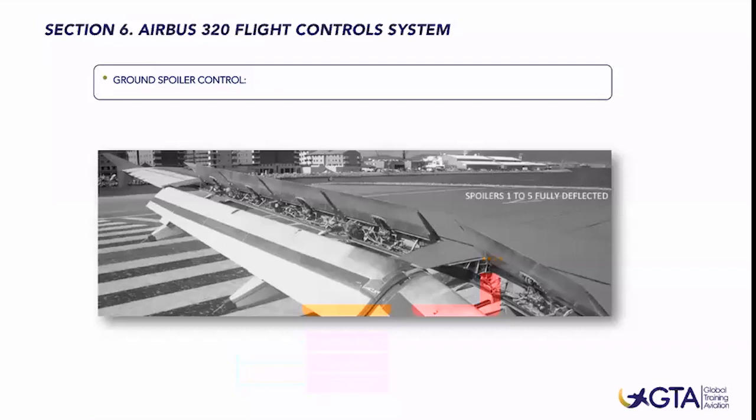Now we're entering a quite interesting part of this flight control chapter, which is Airbus normal law. This normal law is the standard law, the one we are flying under normal conditions, without failures, abnormal situations, or malfunctions in the airplane. So we are flying under this normal law. It covers full 3-axis control. We will have flight envelope protection available, which is great, and we'll talk about this in more depth in the next slides. And we also have load alleviation, or maneuver load alleviation.